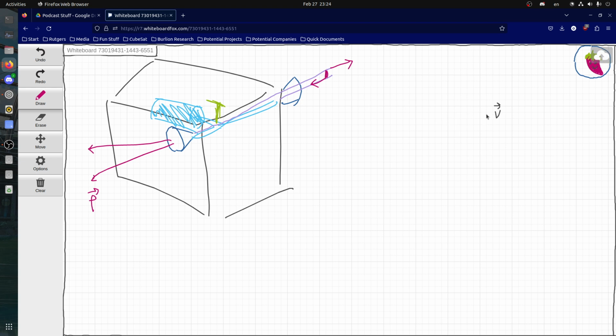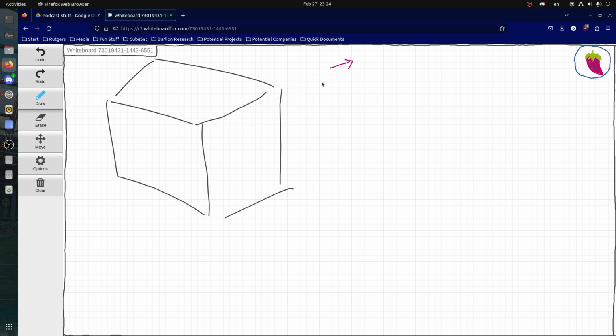One other thing that I forgot to mention: usually this gas is stored at a high pressure, and it has to be cooled. Cold gas, emphasis on cold. To maximize its ability to last a long time, you have to put it under high pressure so you can store a large amount of gas and also get high velocity jets. So yeah, that's cold gas thrusters. We will not be using these because they are a pain, and we don't have the experience to do it. But it is an option, and it is good to know.